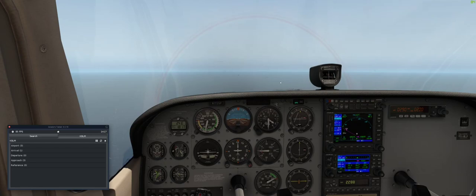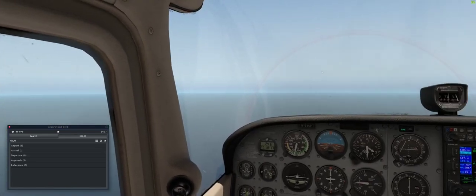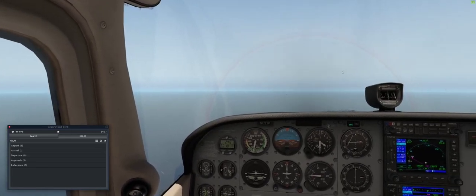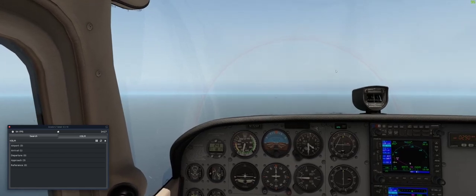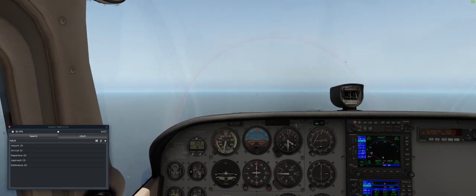So for whatever reason, air traffic control, or in visual flight rules, we might see another aircraft, and we have a responsibility to remain 2,000 feet to the side, above or under that, and maintain that separation. We can't just plow along on our flight plan and say, well, we should have had the right of way. No, it doesn't work that way.